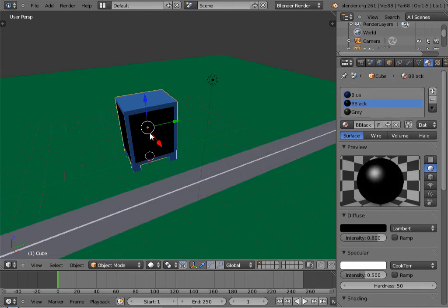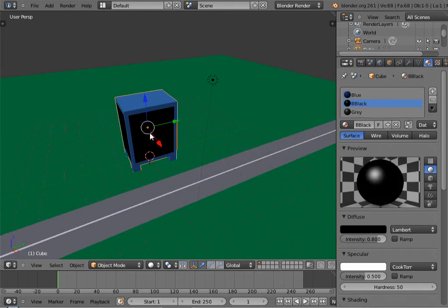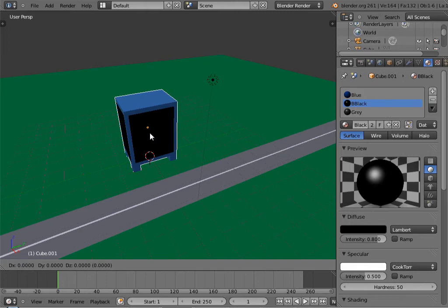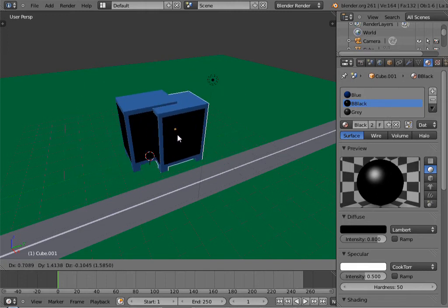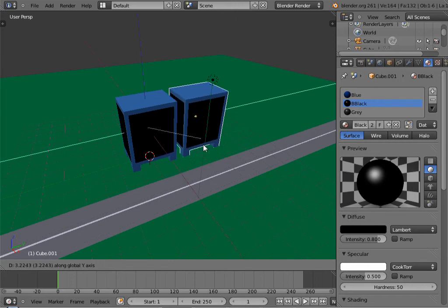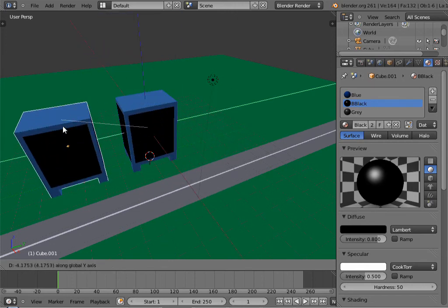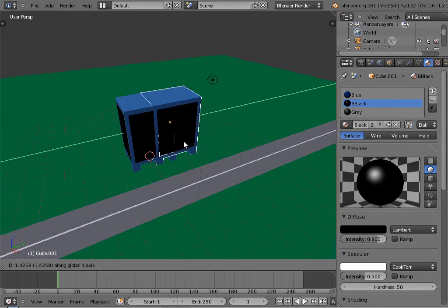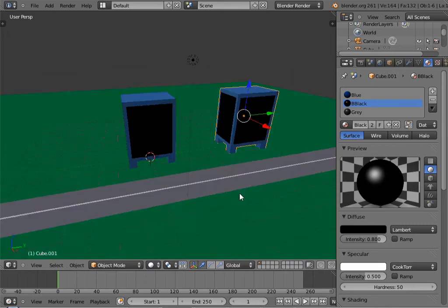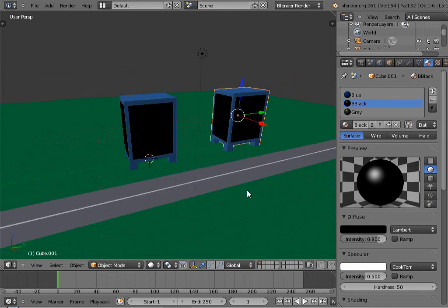Now let's say you want another building. We can simply right click on that, press Shift D, and we get to move it about. Now if we want to make it move only in one axis, we can hold the middle mouse button, and we get to select which axis with this little dotted line. Move it over so it's the Y axis, let go, and we're moving only on the Y axis now. Left click and we put it down, and we have two buildings.